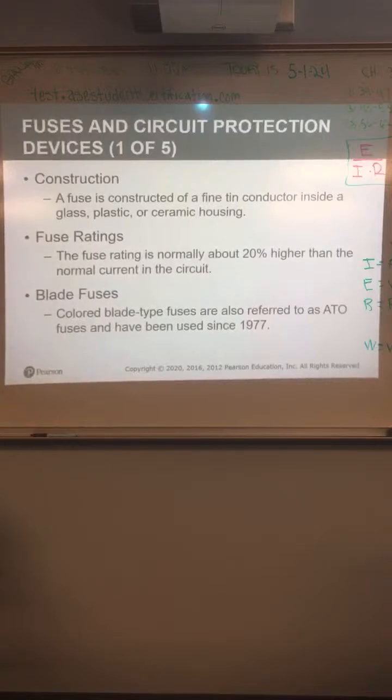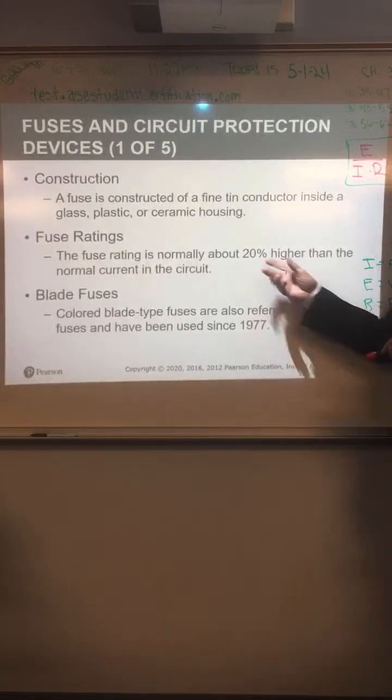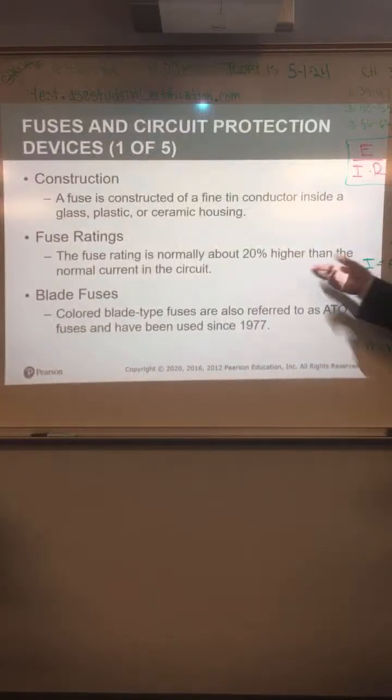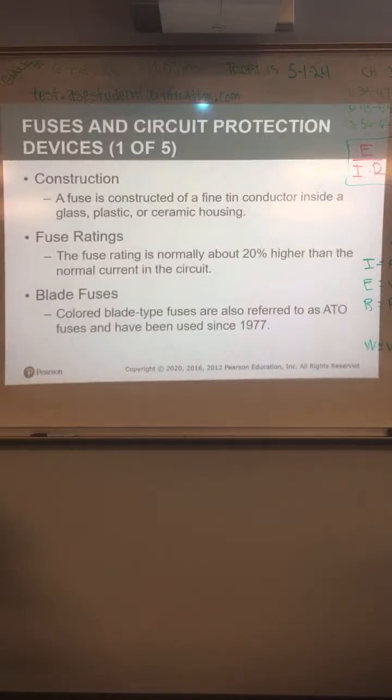Okay? Fuse rating is normally about 20% higher than the normal current in the circuit. We talked about that yesterday for a minute. If a circuit is expected to carry 10 amps, you don't want to put a 10 amp fuse in it, right? Got to go at least 20% higher. Not going to hurt anything. Keeps the fuse from being on the verge of melting every time that circuit is active, okay?